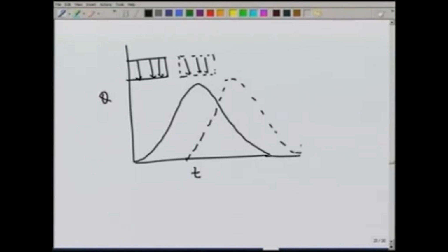Like this. So, these two hydrographs, this and this, they will be same if the effective rainfall hydrographs, ERH, are the same. So, that is the principle of time invariance, that no matter where in time the effective rainfall occurs, it will produce an identical hydrograph.